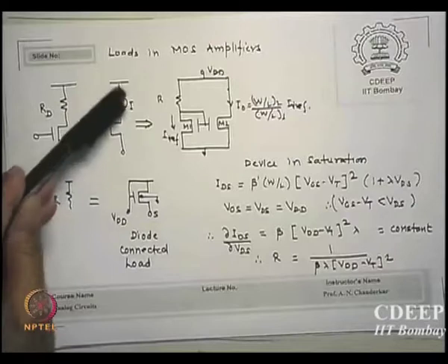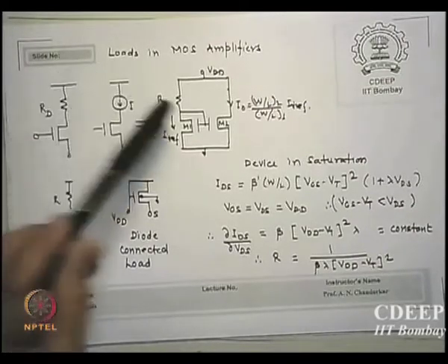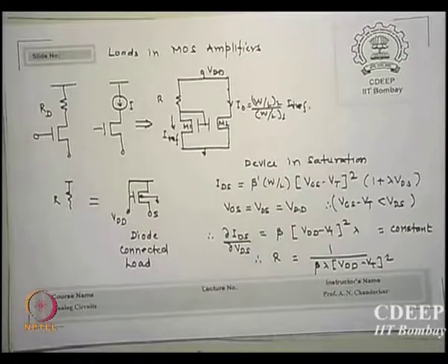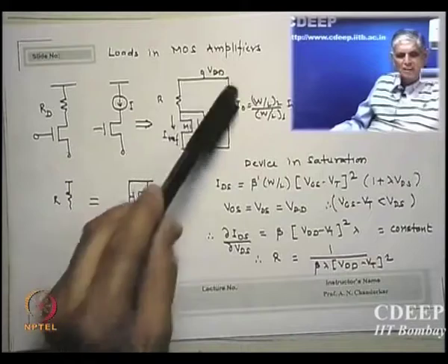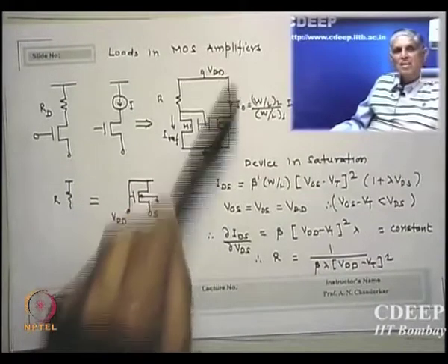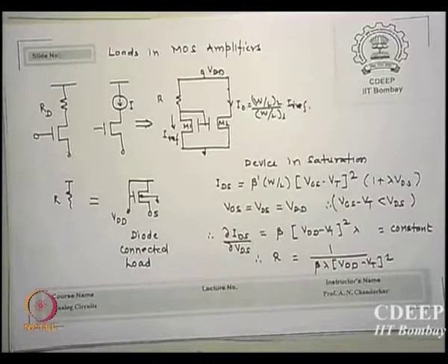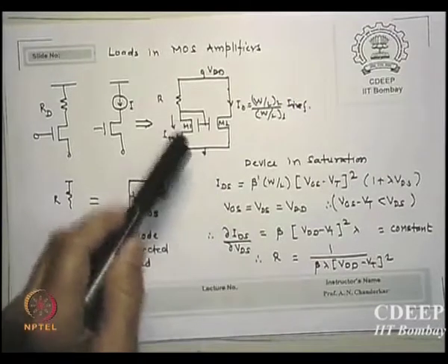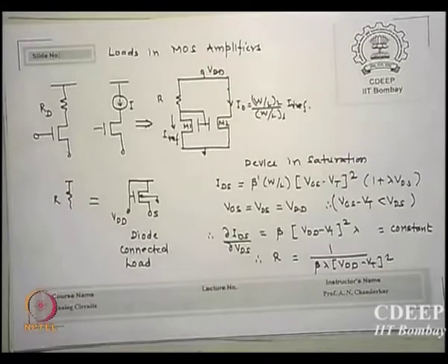So if I put a fixed current source here, which I can create from where? A mirror. You can see if I push a reference current here, I can adjust this current to any value. Is that clear? This I will show you in a diff amp, how I actually bias, but just take it. An equivalent current source can be transferred to an amplifier as a load by simple current mirrors.